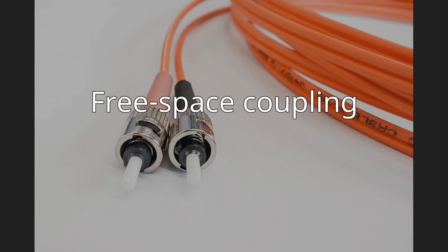The connector is simply plugged into a pre-aligned fiber-optic collimator, which contains a lens that is either accurately positioned with respect to the fiber or is adjustable. To achieve the best injection efficiency into single-mode fiber, the direction, position, size, and divergence of the beam must all be optimized. With good beams, 70 to 90% coupling efficiency can be achieved.